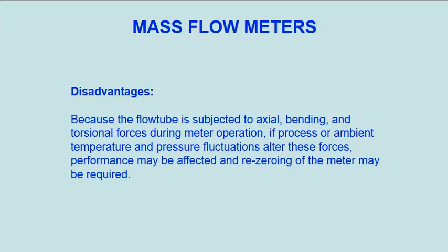Disadvantages. Because the flow tube is subjected to axial, bending, and torsional forces during meter operation, if process or ambient temperature and pressure fluctuations alter these forces, performance may be affected and re-zeroing of the meter may be required.